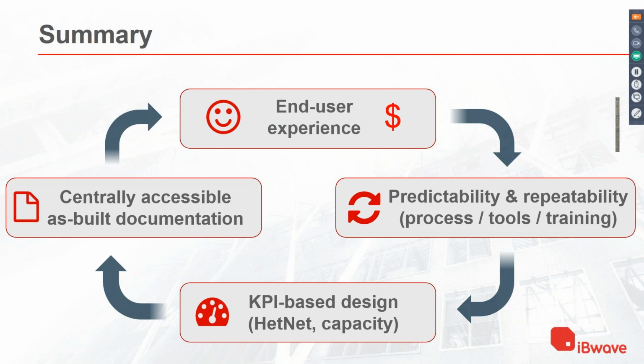Well, first of all, there's iBwave Mobile, the iBwave Wi-Fi, and iBwave Wi-Fi Mobile. So the iBwave Wi-Fi is on the PC device, and you can do a design, and obviously with mobile you can also do additional site survey work and design, but there's a lot more capability in the PC product, because you can do much more detailed capacity planning. You can do a much more detailed modeling of the venue. The propagation is a bit more accurate because we use fast ray tracing.